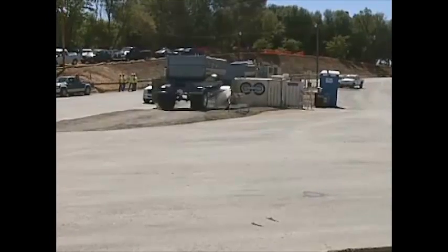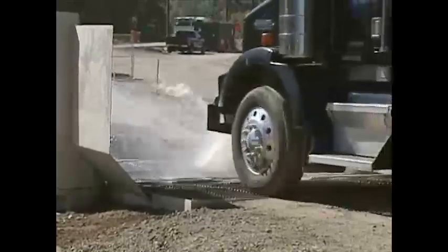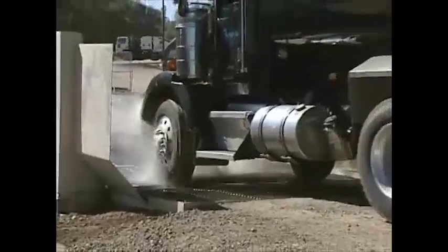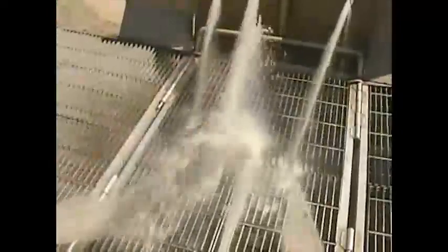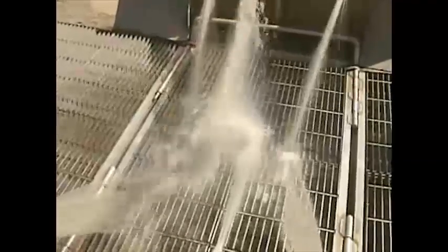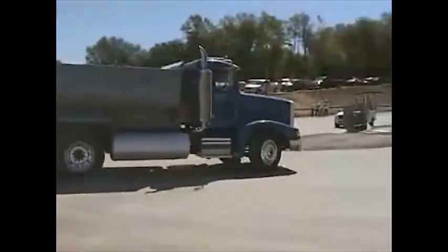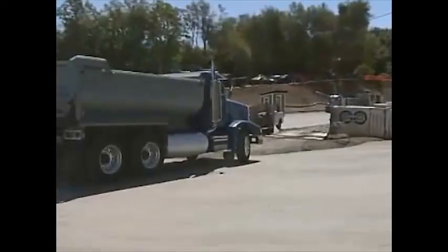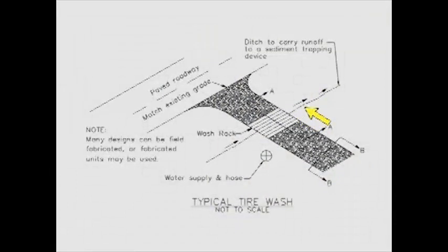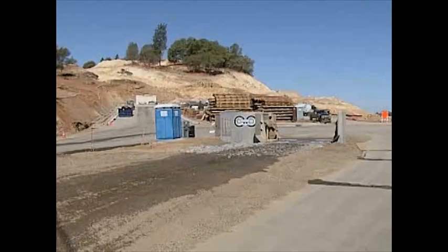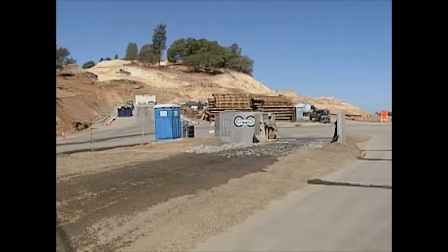by the resident engineer. The design of this BMP must account for the anticipated traffic load at the construction site. It must incorporate a wash rack on a pad of coarse aggregate, a supply of water, a turnout or double-wide exit to avoid having entering vehicles driving through the wash area, and a drainage ditch of sufficient grade, width, and depth to convey the runoff from the wash area to a sediment trapping device. Although site conditions dictate design, the tire wash area should be constructed on level ground.